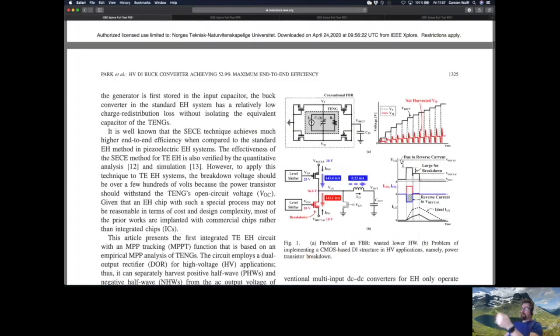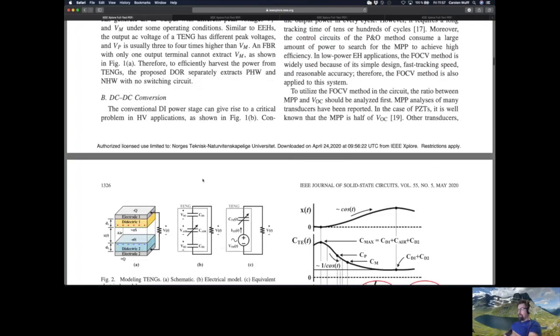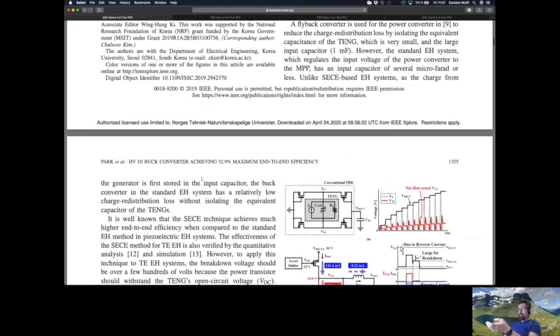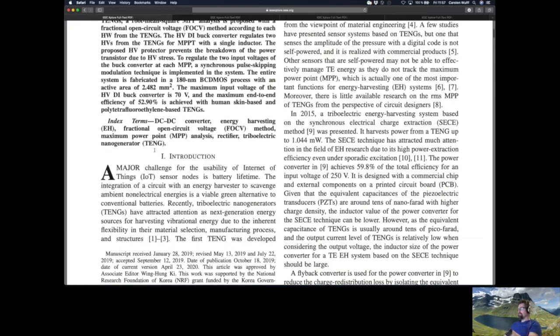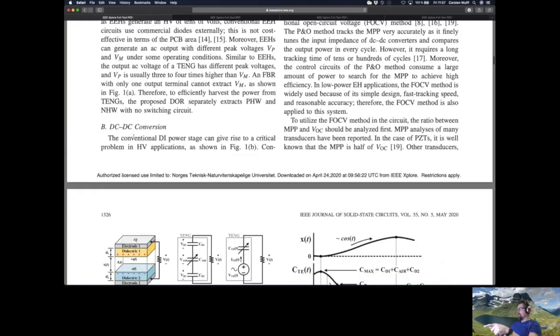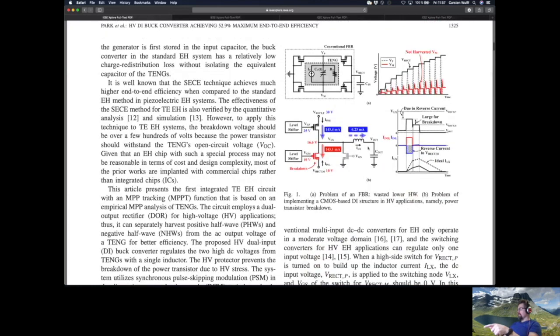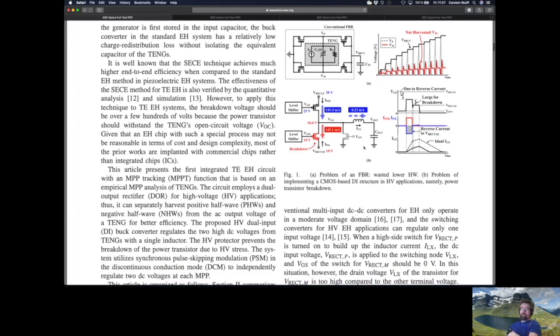This energy harvesting system has some special characteristics where you actually need some special, what was it called? Half wave harvesting. Okay, but there's supposed to be a DC-DC conversion here. In here. Yeah, so here we can see there's some switches and the inductor at the output. So this is actually the DC-DC converter. So you have pulling high, pulling low, and then the same thing. But this paper will not explain this part that well. It will assume that people will know how bucks work.